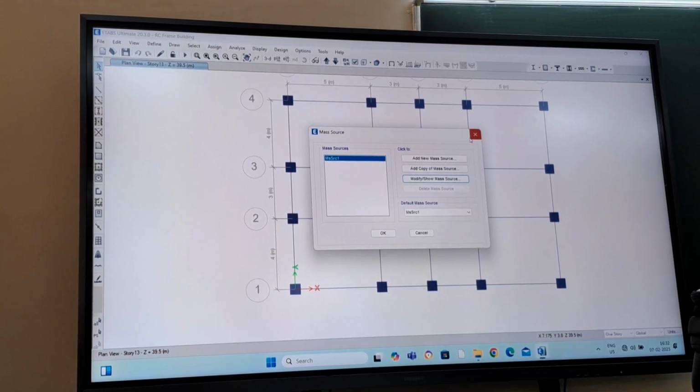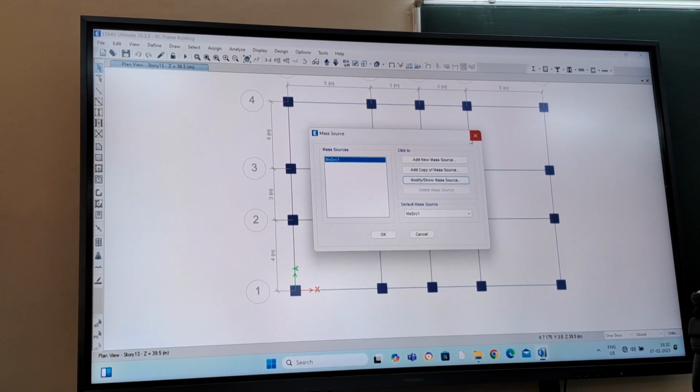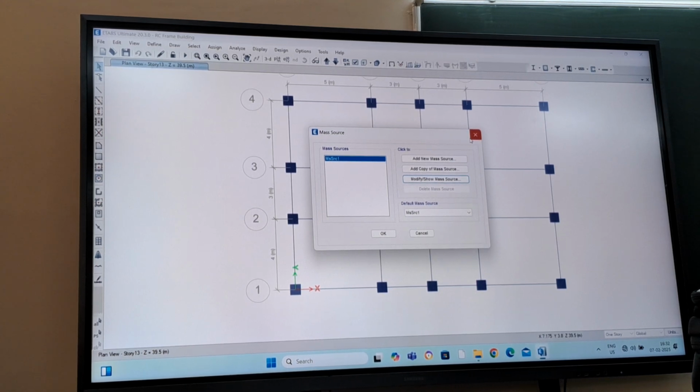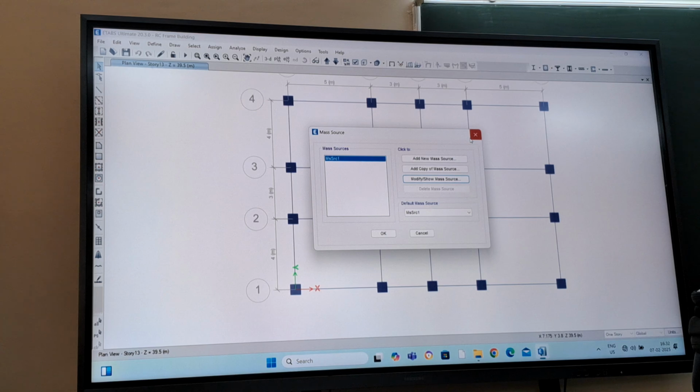Suppose the bottom story I have 500 by 500, immediately on top of that you have 400 by 400. So how will the reinforcement be continued? That is your question. You can provide a little bending, that is acceptable. Where that size reduction occurs, at that point you bend the rebar a little bit, bring it a little bit inside, then continue upward.